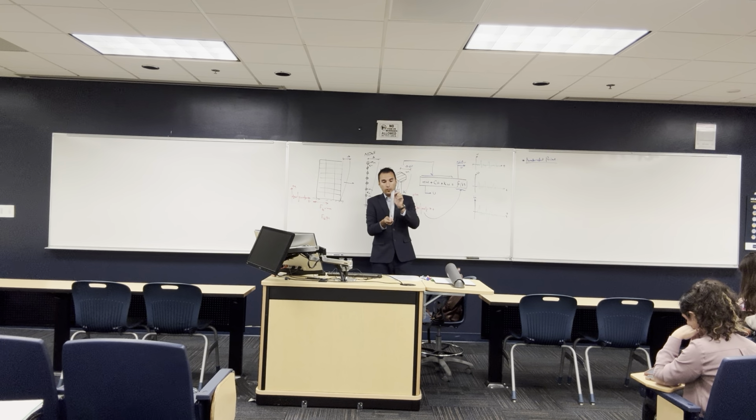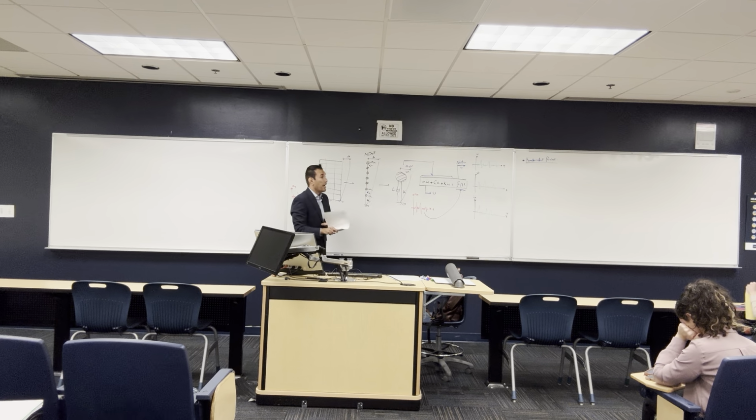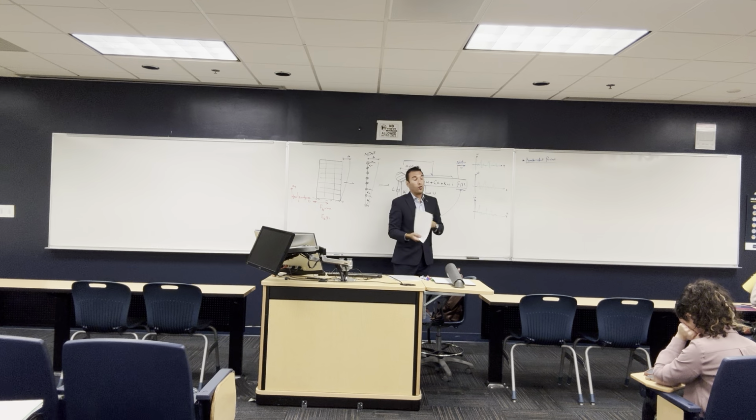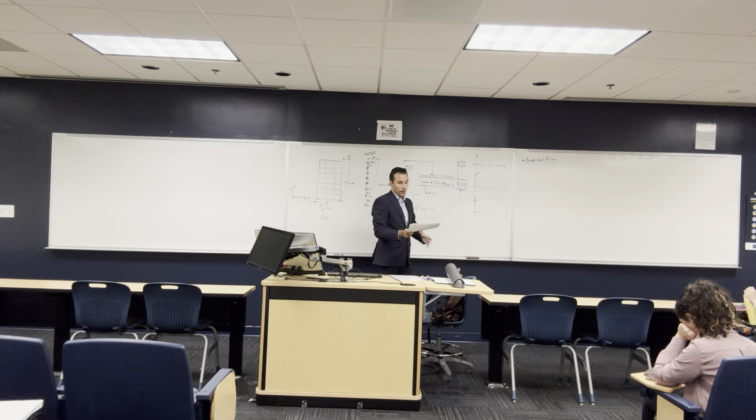So this is the first movement. When we say the natural period, it is the time that this building needs to make one cycle around itself, like goes this way, goes this way, and comes back to the original position. That's the fundamental period of the structure. It depends on the mass of the structure and the distribution of the mass, and on the stiffness of the structure, how stiff it is. And also on C, we are including the damping, but I'm not gonna talk about it right now. Let's talk stiffness, all right?